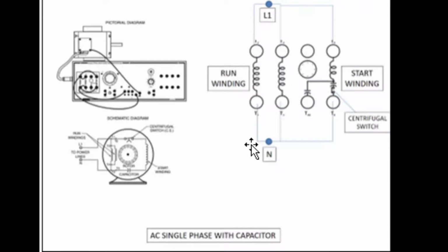All right, if you now look inside the motor itself, we've got two run coils like we had last time, and the third coil is attached to the capacitor. They're a little bit easier to see here on the right hand side. We've got the two run coils that are also in parallel with the start, and then there's a capacitor.